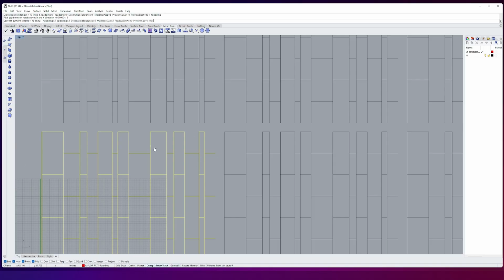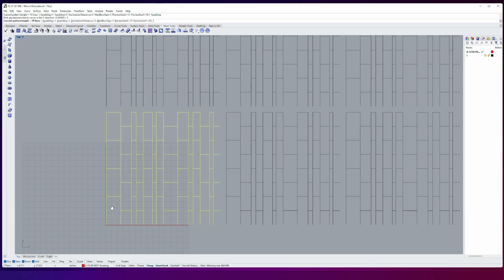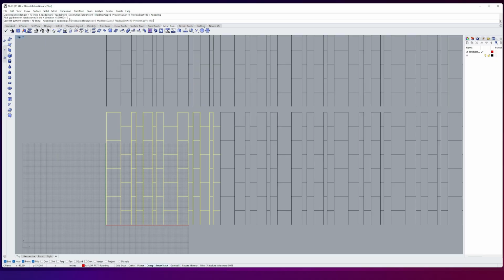For these types of patterns where we're repeating things for like floors or, you know, ceilings, and you want it to be perfectly tileable, you'll want your padding to be 0 and 0. But if you have one large shape, say you made a star shape or a triangle or octagon, whatever that shape is, if you wanted to add padding around it, you could before you export this as a PAT file. So I'm going to set my X and Y padding back to 0.